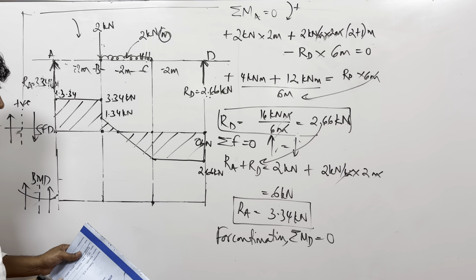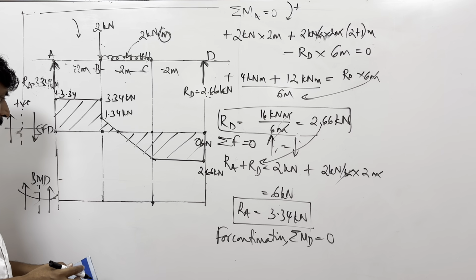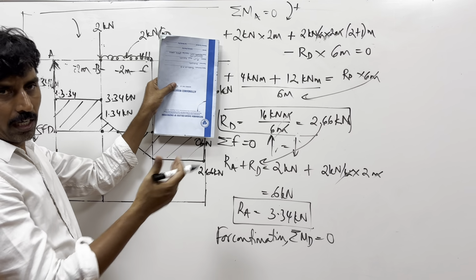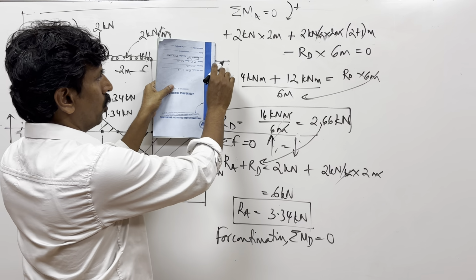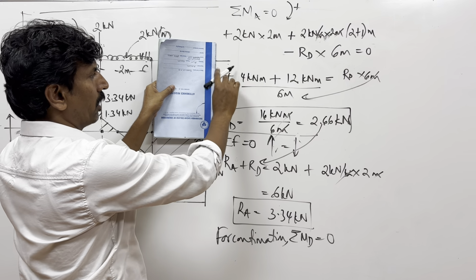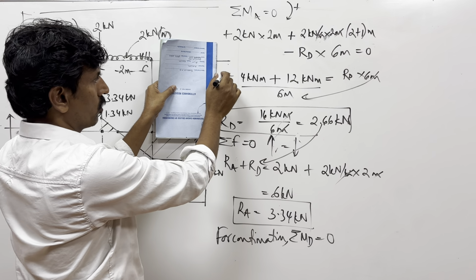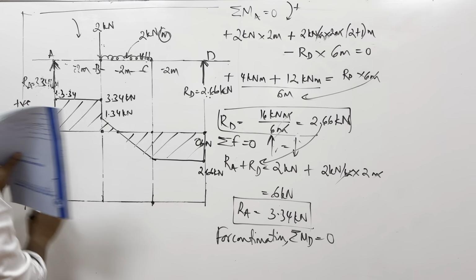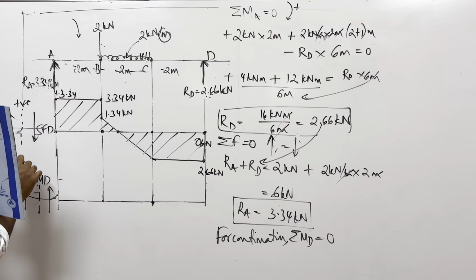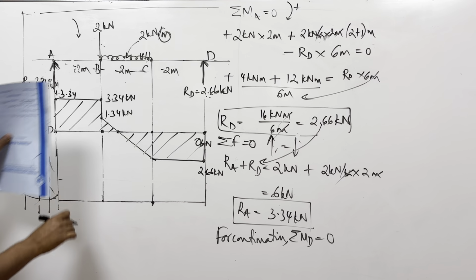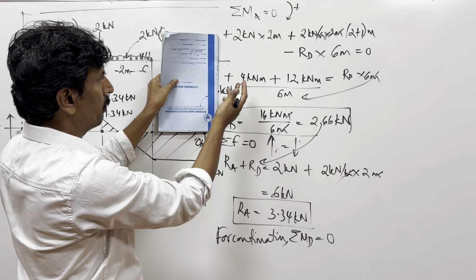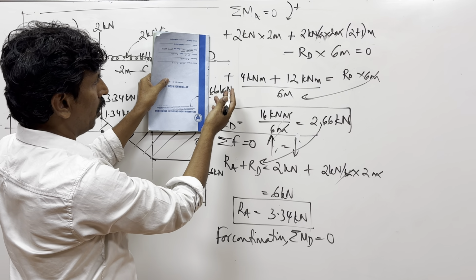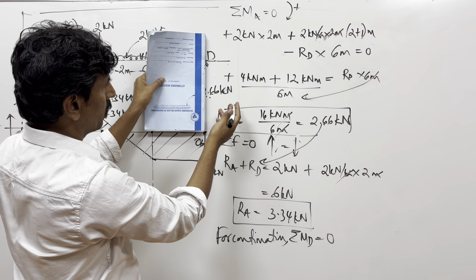Okay. Now here, the bending moment diagram. I am again starting from the right side because we used to do that. So here, are there any forces? No forces, no moments. What is bending moment basically? Bending moment is force into distance. First of all, there are no forces, so there can be no bending moments. Even now there are no forces, no bending moments.